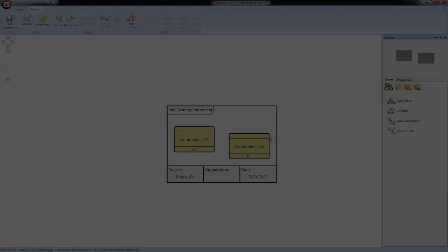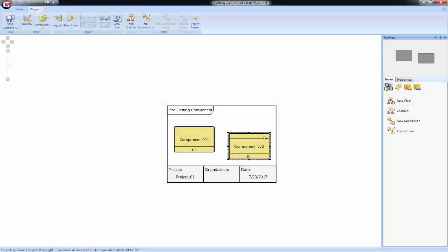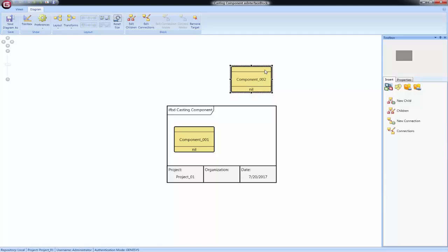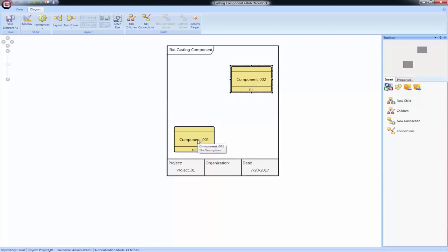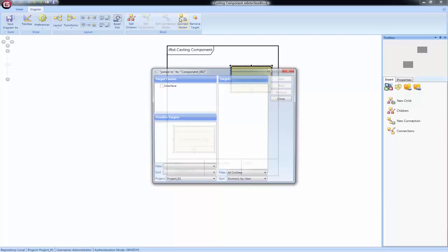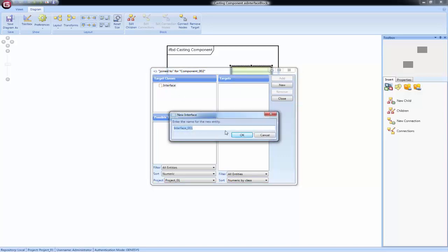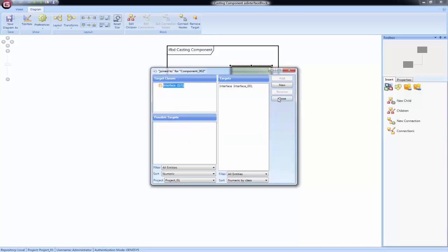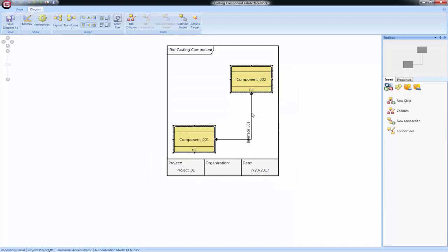The interface block diagram is a free-form diagram. GENESYS begins with a simple layout for the nodes, but you can customize node positions as desired. Individual lines can be repositioned as well. Drag the handle at the connection point to control where the line connects to the node.